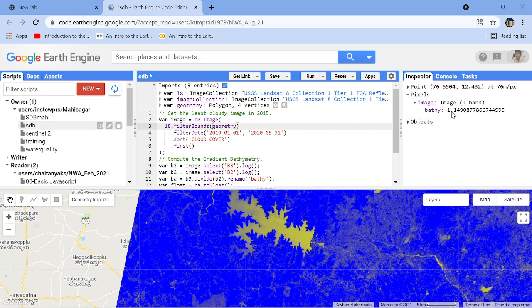So it is showing 1.14 is the pixel absorption for a particular band. Right now I am using band 3 and band 2 data alone, band 3 divided by band 2, and I am using it. So you will appreciate it. See, in the land portion there is 0.97, whereas within the water you have a gradation. It has become 1.14. So this is the beauty of it.